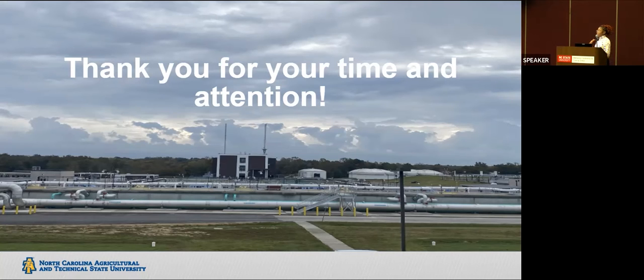Yeah. So like you mentioned, depending on the industry that produces the wastewater, the parameters of the wastewater are going to be a bit different, but the idea, the concept still works. Since we're removing carbon and nitrogen, the concept is still going to be the same across the board, but it's just going to be different rates of carbon removal, different rates of nitrogen removal.